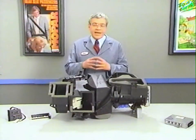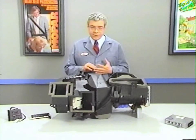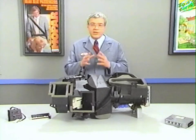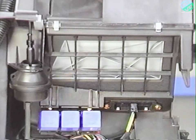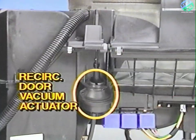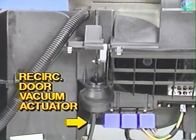Earlier, when discussing ACM outputs, we briefly covered plenum air door operation. Now, starting with the vacuum-operated doors, let's take a closer look at exactly how the plenum directs air where it's needed. The air recirculation door, located just to the left of the air control module, has 2 positions. One allows outside air to enter the plenum, the other recirculates air from inside the car. The spring-loaded vacuum actuator operating the recirculation door has only one vacuum line going to it.